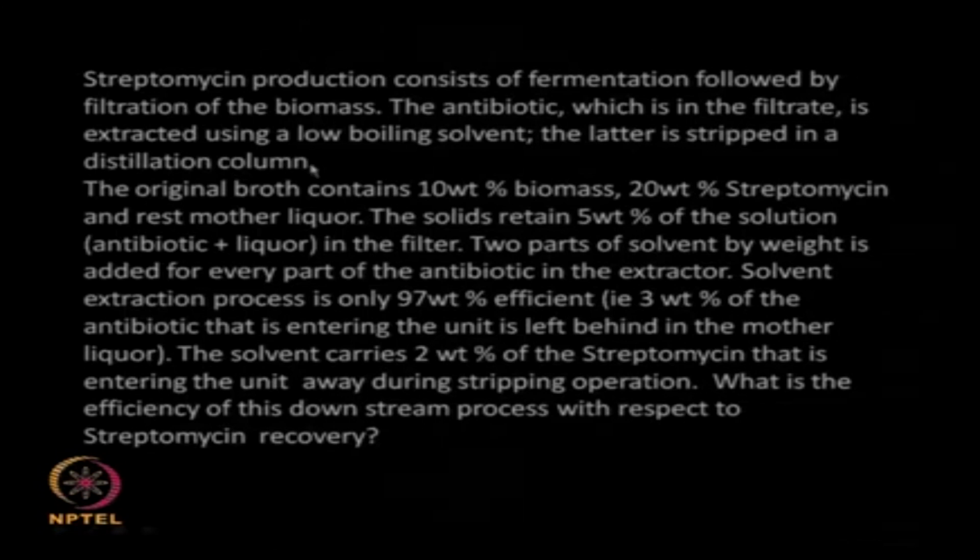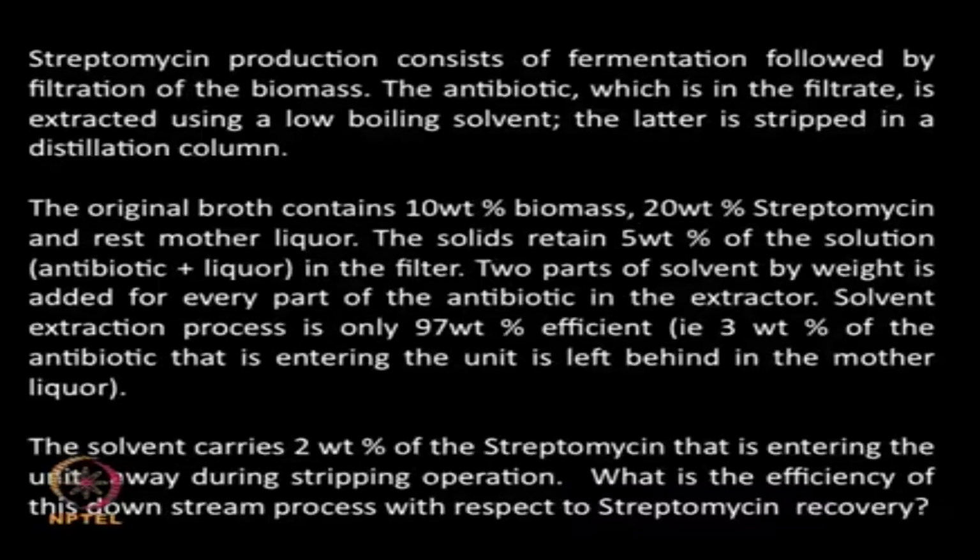Each step is going to have some efficiency. It is definitely not going to be 100%, but it will have very good efficiencies. So the idea is to determine what is the total efficiency of the entire downstream process. The original broth contains 10 weight percent biomass, 20 weight percent streptomycin and the rest mother liquor, that is the liquid. So we are interested in this particular product.